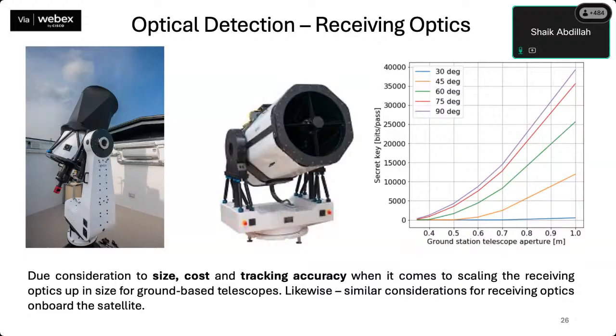And we've talked about some of the difficulties of the optical link, such as diffraction losses being the most dominant loss within our optical link. We've talked about pointing losses that arise not only because of the beam wandering, but also because they are limited by the fast steering systems that we can have on our ground station and our satellite. And we've talked about the size of the receiving optics and how that plays into our link budget.